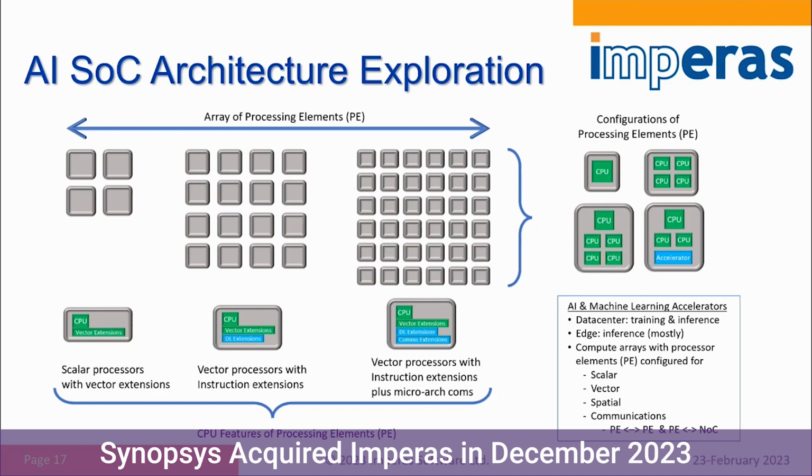For example, on an AI SoC, customers have used us to answer the configurations of how to configure, for example, at each processor element level. How many cores there should be, how big the control processor should be, should there be accelerator within the PE? Or at the whole chip level, scalar versus vector versus adding custom extensions and so on and so forth. So we're great for even early on, before you're ready to start the RTL design.